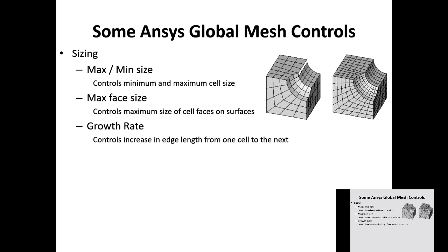mesh at the walls, because in most of the cases you need to apply wall boundary conditions, or inlet boundary conditions, or exit boundary conditions. So at those faces, you need a reasonable mesh to accommodate whatever physical properties you have.